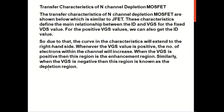Now let us go to the transfer characteristics of the N-channel depletion type MOSFET. The transfer characteristics are similar to those of a JFET, where the characteristics define the relation between ID and VGS for a fixed value of VDS. For a positive VGS value, we can also get the ID value, so the curve in the characteristics will extend to the right hand side. Whenever the VGS value is positive, the number of electrons within the channel will increase.